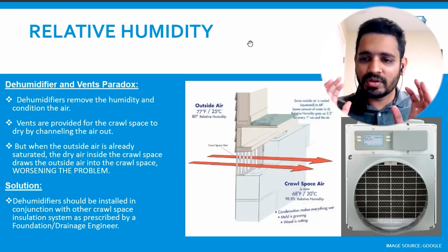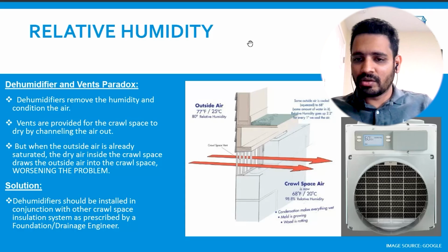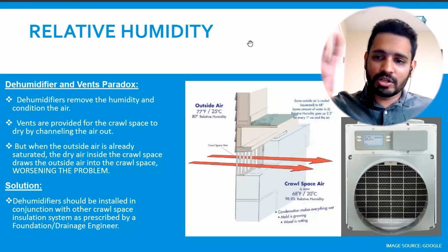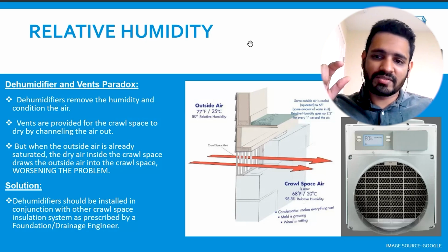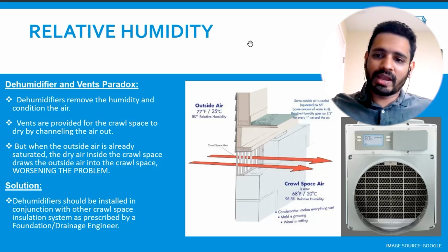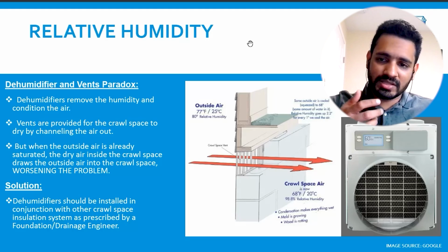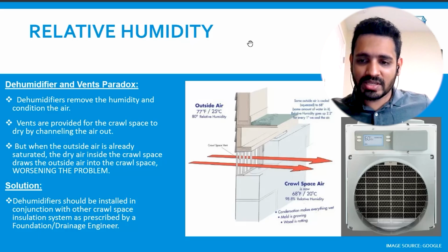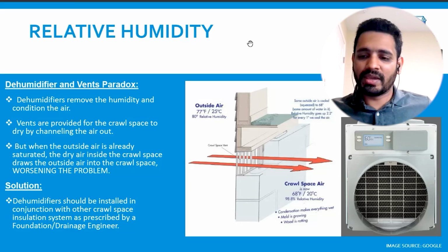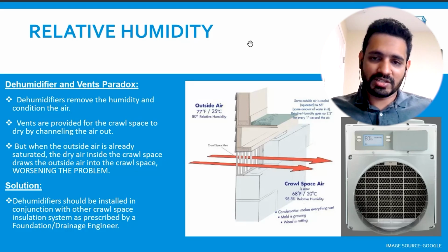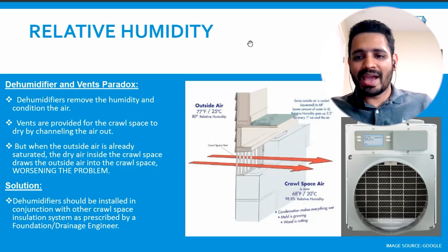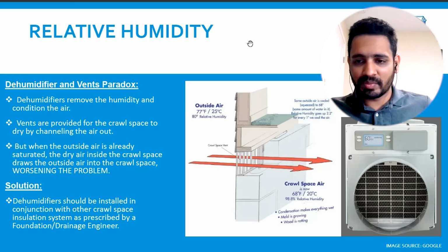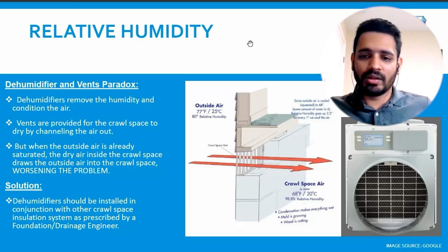If you just put dehumidifiers in a crawl space, that is not going to regulate the moisture condition inside a confined space. Even crawl space vents come with humidity or temperature-based fans that circulate the air, bring the dry air from the outside in, and then siphon out the damp air outside. Again, if you don't have the crawl space sealed properly first, you're not actually making a huge change by these installations. So it's important to understand when and where to install these dehumidifiers and to find out if they are actually going to serve the purpose that you want before you spend all that money.